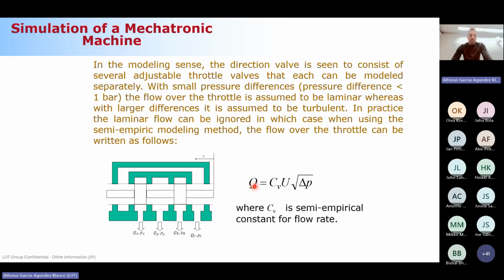So that is why, when the pressure difference is small, from a numerical point of view, it can be a good decision to model it as laminar, okay? Because the derivative of the turbulent flow can lead you to a singularity. But in practice, in most of the situations, we use the turbulent flow. I just explained this derivative issue from a numerical perspective for doing simulations. We will do an exercise where I will show you this, but in practice, in most situations, you model the volumetric flow rate with the turbulent expression. Is it clear? Yes? Perfect.